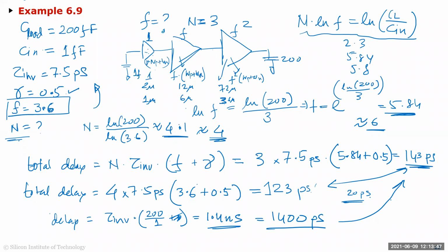If you go from 1 stage to 3 stages, even with your non-optimum one, you get a 10x improvement, and that's good enough for me. After that, it's just squeezing everything out of it. If I'm just designing a buffer to get the maximum benefit, I'll just do 3 stages, do 4x or 3x, and I know it's going to be pretty close to the minimum one. Okay.